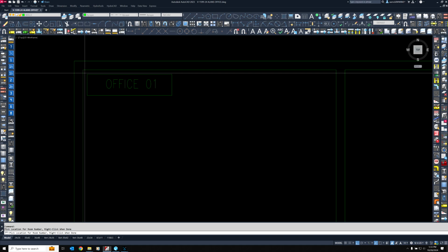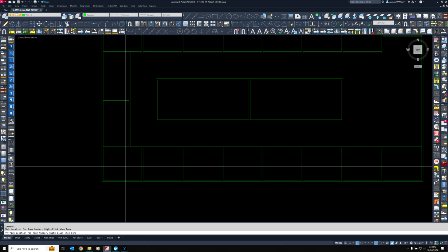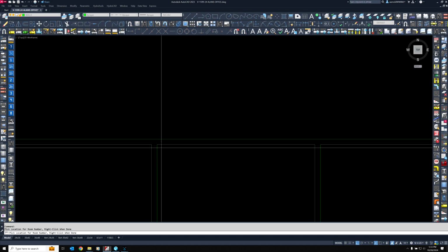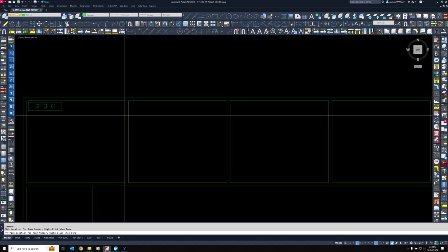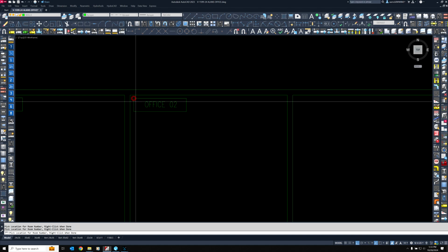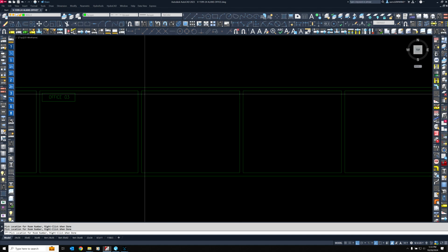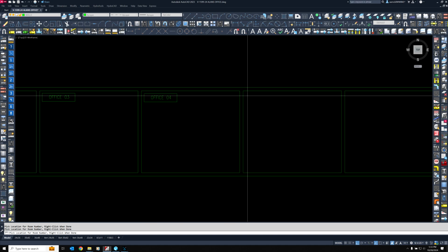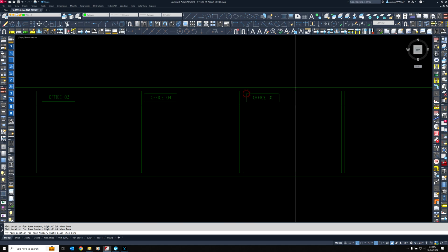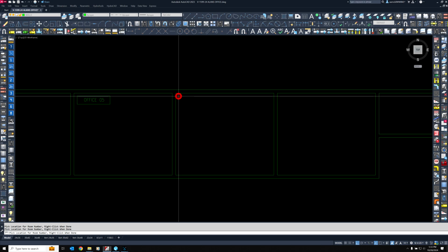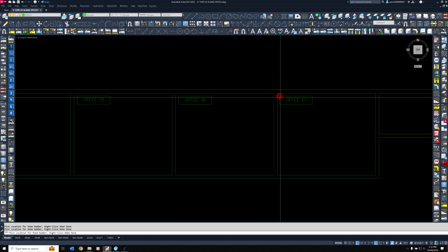You can see now where the insertion point is. It's that top left corner. So every time you go to a room, think about where it's about to drop it, and you can save yourself a lot of time in the cleanup phase. Odds are the outside wall in this room, we will not have any pipe or sprinkler heads, and it will help keep things a lot cleaner.